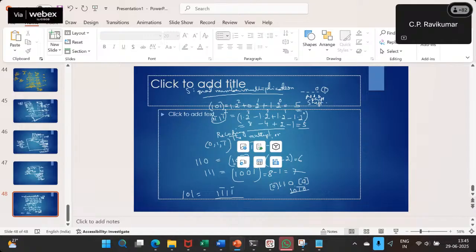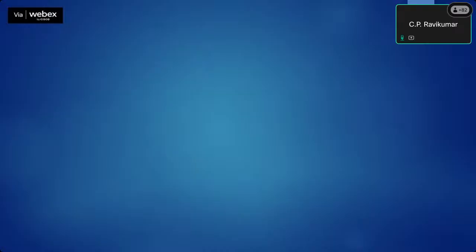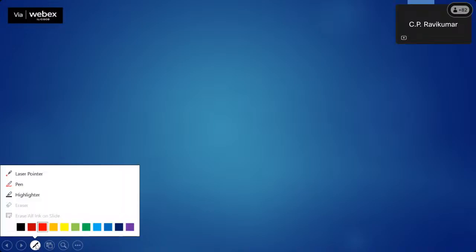So if you allow multiplication, if you allow subtraction also, then it may be faster. That is the idea. The earlier multiplier works worse when it is 1, 1, 1, 1. Imagine if this was a shift and add multiplier, then every one will invoke an addition.